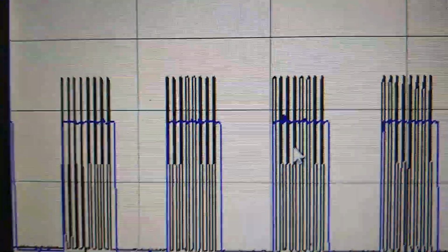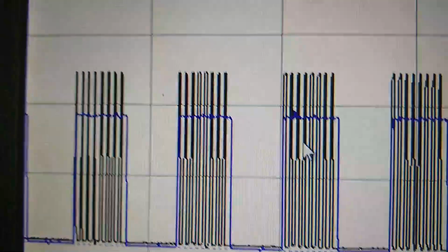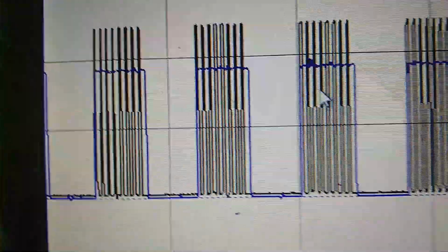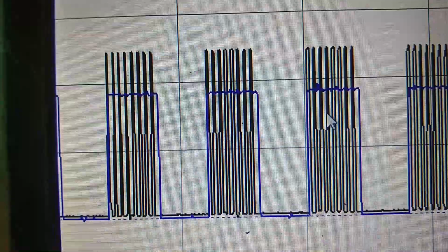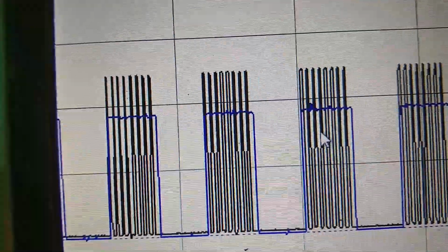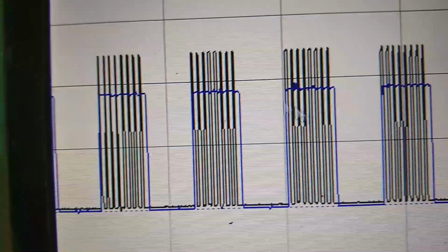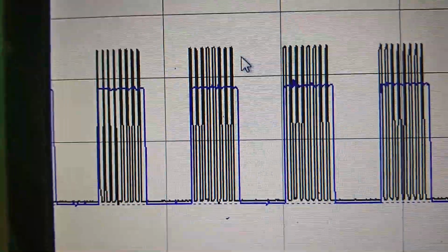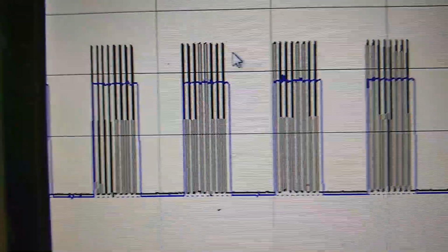So here in each positive pulse, 1, 2, 3, 4, 5, 6, 7, 8 pulses are there. Okay. So just you can take this part. How many pulses are there behind the comparator, for the data one, the logic one? 8 pulses. So here we complete the demodulation part of the ASK.